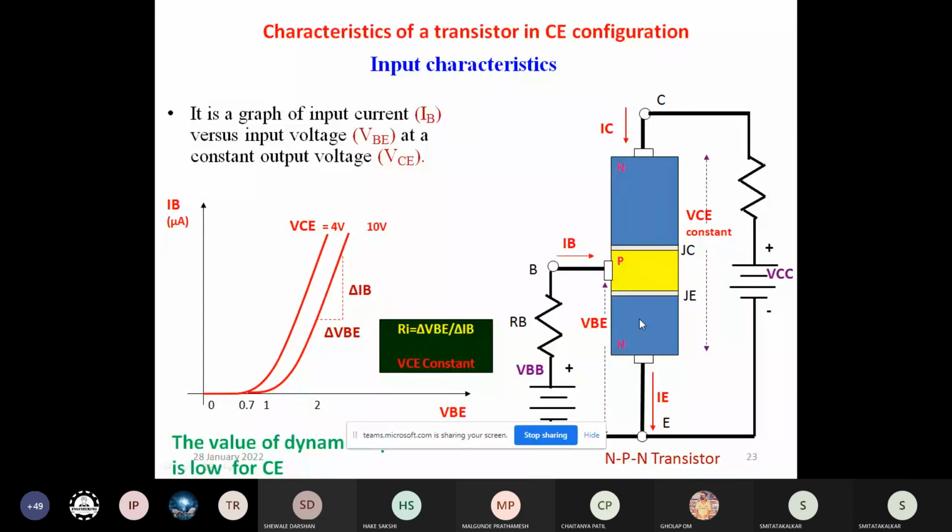A positive charge is created, and current is conducted through the emitter terminal. If the P region of the transistor is operated with a negative charge and the N region with a positive charge, that junction is known as the forward biased emitter-base junction. It is forward biased and current flows through the circuitry.